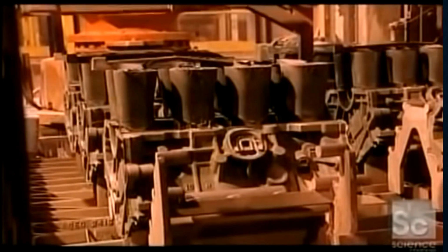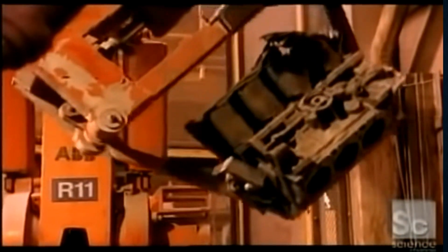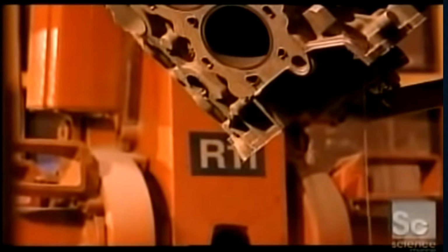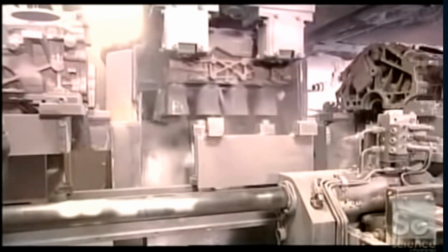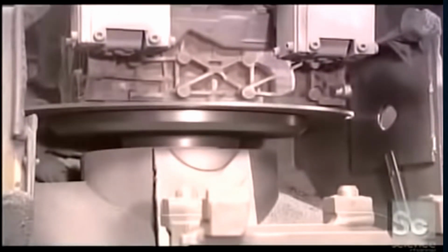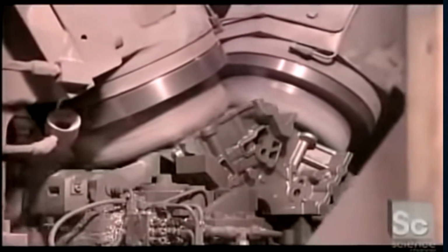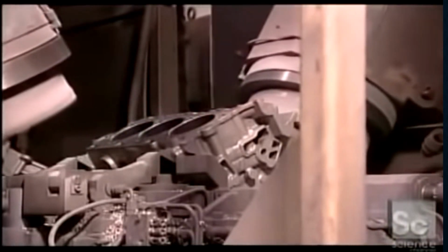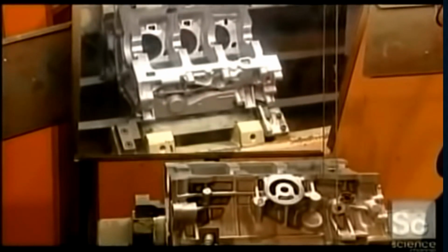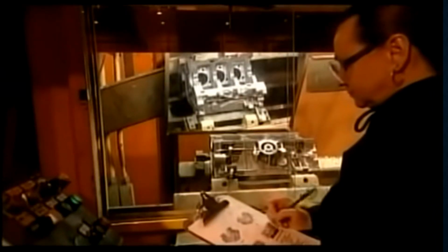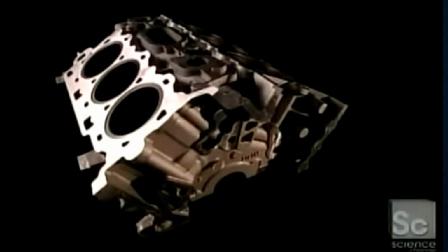After that casting, we start finishing it. These finishing processes are such as surface grinding. Firstly, cut the runners and risers. After that, finishing of the surface. Our final product is ready.